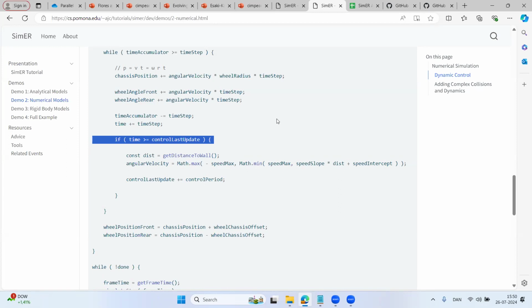You just want to simulate, see what the behavior is, reduce it, maybe do a sort of binary search process. If 0.1 seconds doesn't give you good behavior, then go down to 0.01 seconds. If that doesn't, 0.001. If that works, then maybe double, doing a sort of binary search, until you find some good bounds. But your controller time shouldn't update every physics time step.